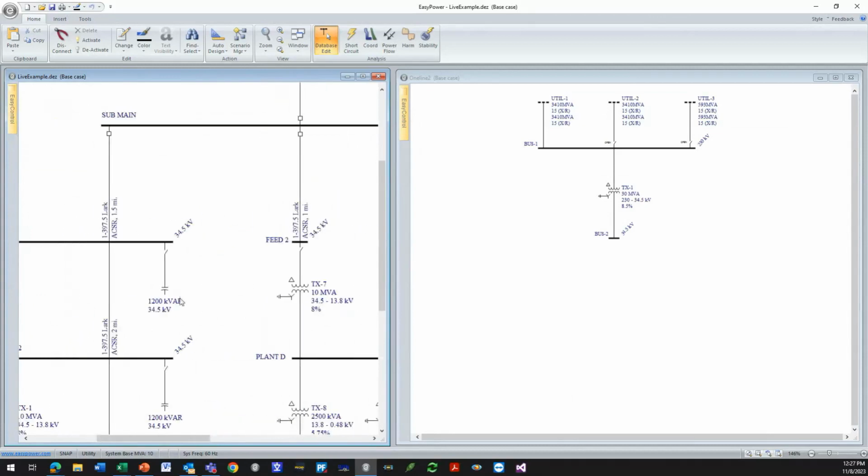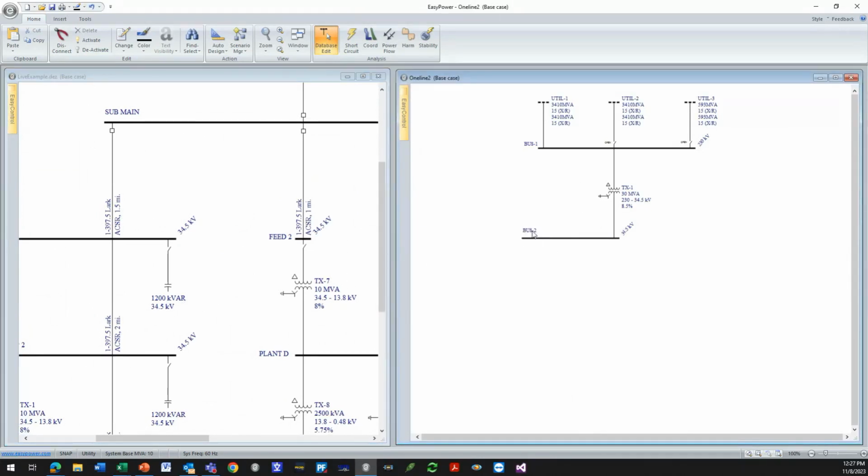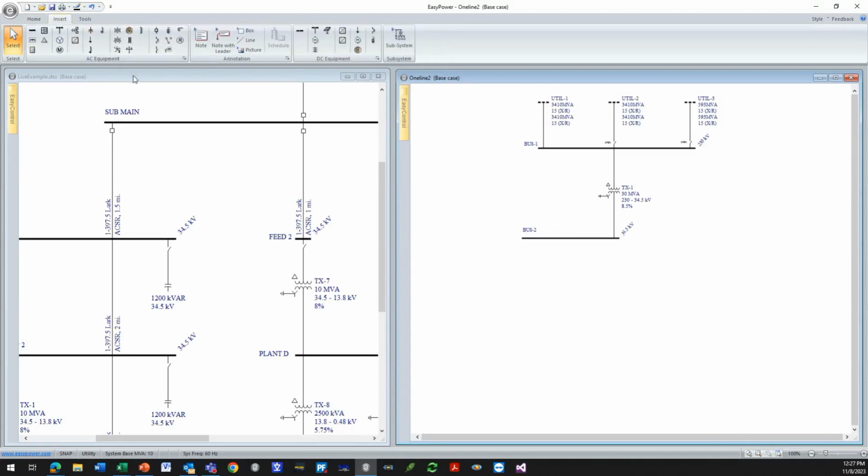And I'm going to model one of these, and the rest of them, I'm going to just jump back and use this model, but I'll show you how I would actually build this, starting with at least one of the lines. So I would put in an overhead line. Once I've got my overhead line in, put a bus at the end.